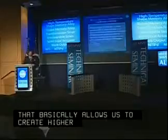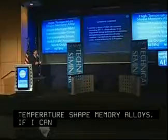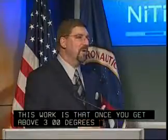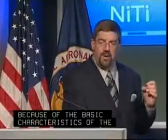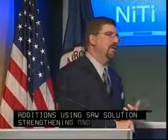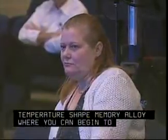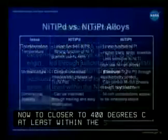So if I could have the next slide. What we've basically found out from all this work is that once you get above about 300 degrees C, it becomes very difficult to create a high temperature shape memory alloy because of the basic characteristics of the individual phases. But there are things that you can do. You can start engineering materials now by adding alloying additions, using solid solution strengthening and precipitate strengthening in order to develop an engineered high temperature shape memory alloy, where you can begin to push the usefulness of these materials now to closer to 400 degrees C, at least within the systems that we're working with. If I can have the next slide.